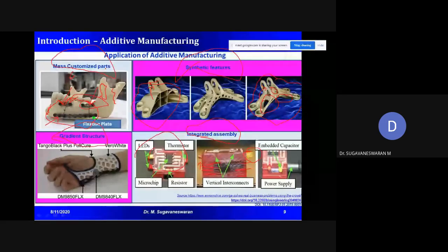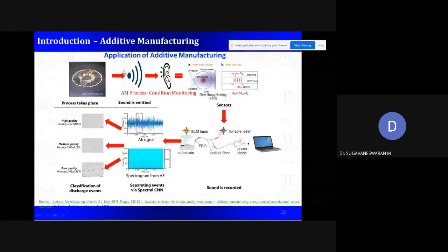And additive manufacturing is also one of the suitable processes in a smart manufacturing setup. So what is smart manufacturing? A traditional machine with some sensors, right? That is what is referred to as smart manufacturing. If you have a CNC lathe with automatic identification of tool wear, vibration, and dimensional variation of a part, with sensors and a monitoring mechanism in a closed loop system, where it can be corrected by a robot or a manual intervention, then that particular process is called smart manufacturing, right?